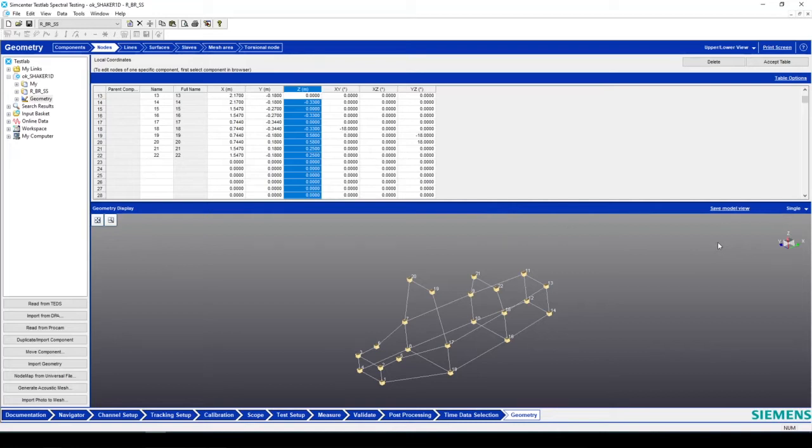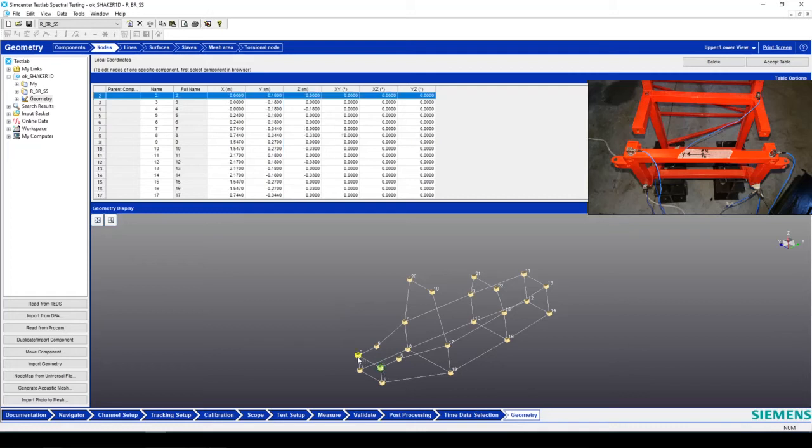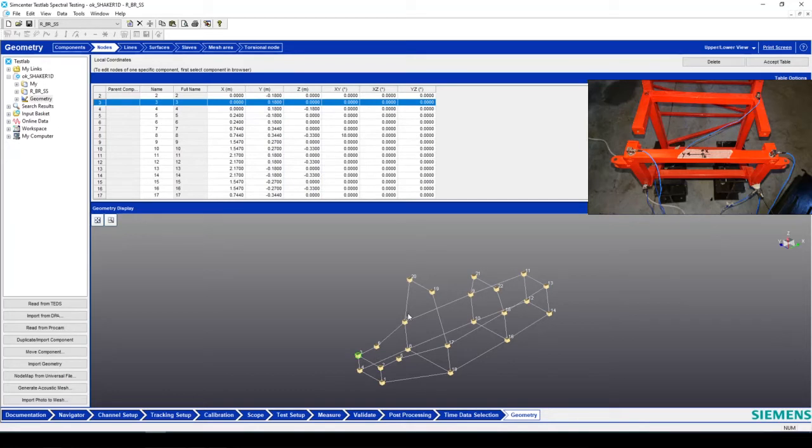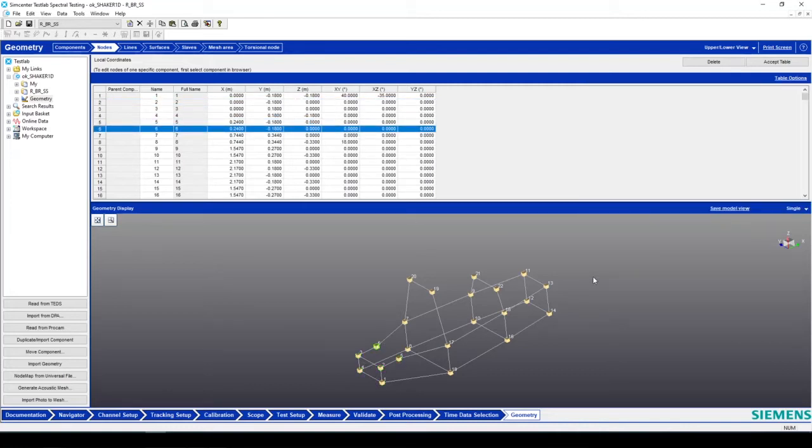The choice of the position and the orientation of the absolute reference frame is up to you, it is totally subjective. Of course, I advise you to choose a point that will make the analysis easier, for instance a symmetrical axis of your structure. Basically I have put the origin of the absolute reference frame here between point 2 and 3, in the middle along the symmetrical axis of the car, and therefore all the points are symmetrical in pairs, so 1 and 4, 2 and 3, 5 and 6 and so on. They have the same X and Z coordinates, and the Y is of course symmetrical with respect to the origin.